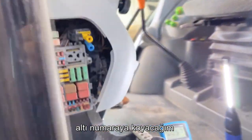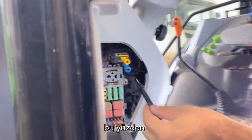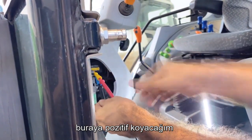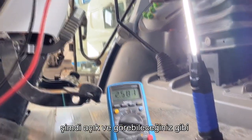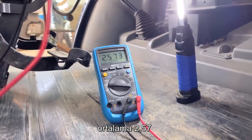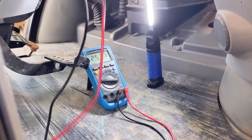I expect to have around 2.7, 2.8 volts. So I'm going to place ground here, and I'm going to place positive here. There is nothing, and that's because we have ignition off. Now it's on, and as you can see, we've got an average of 2.57, 2.56.